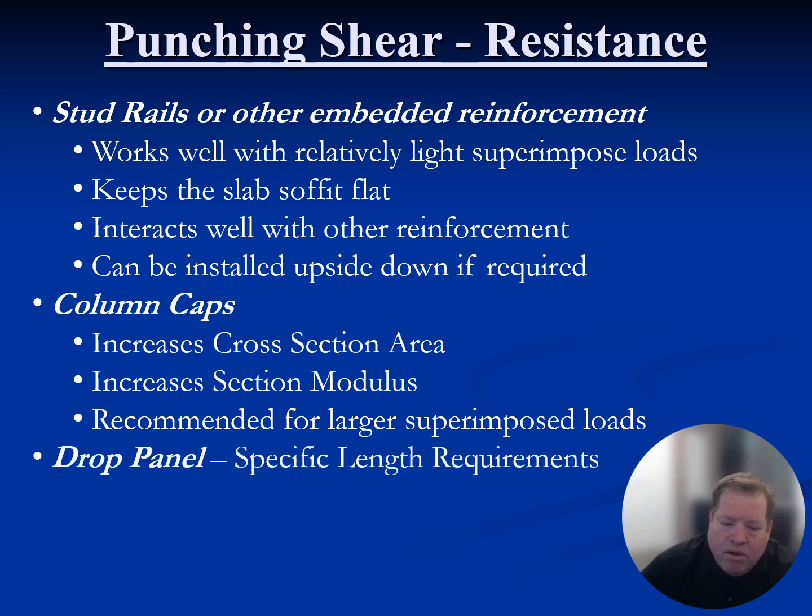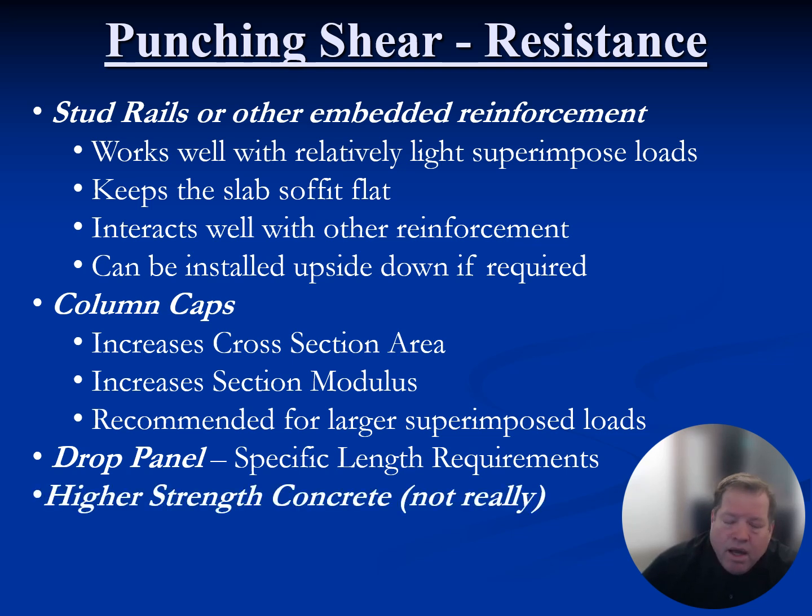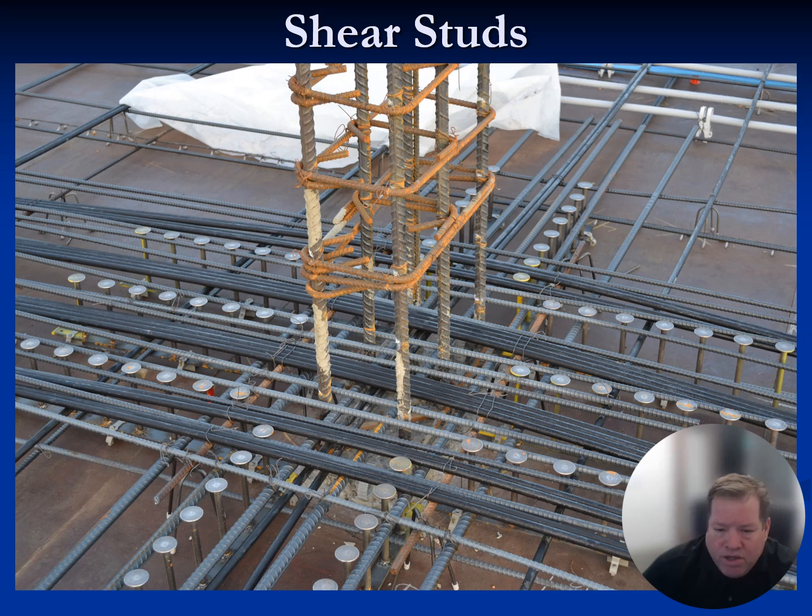The drop panel that you use in rebar concrete, you can use in PT. It does not apply, though. You don't have to use drop panels in a PT slab. You can use whatever you want. If you're more used to the drop panels, great. Use those for punching shear if you would like to. In theory, you could use higher strength concrete, but if you're using the PT equations for punching shear, once you go past 5,000, it's not going to help you. So if you can use higher strength, look at using the rebar only equations.